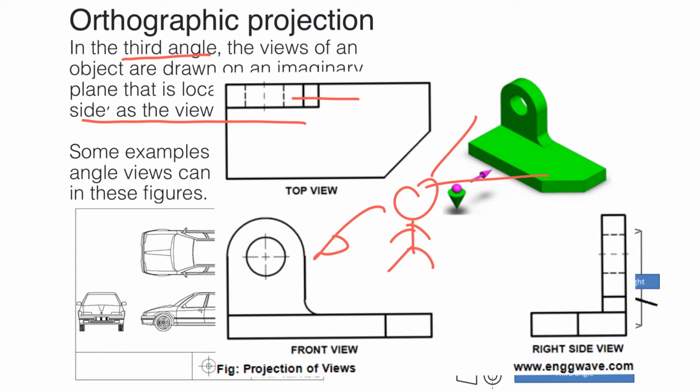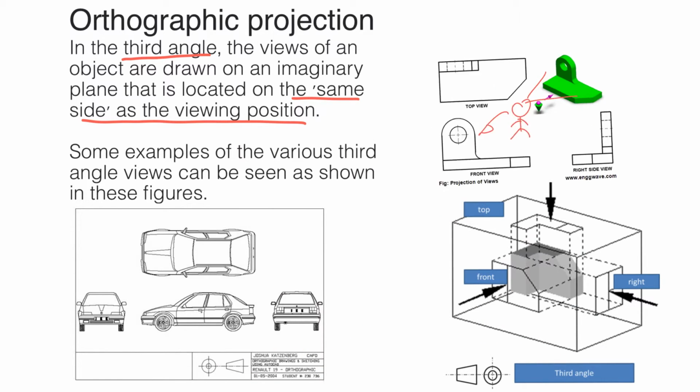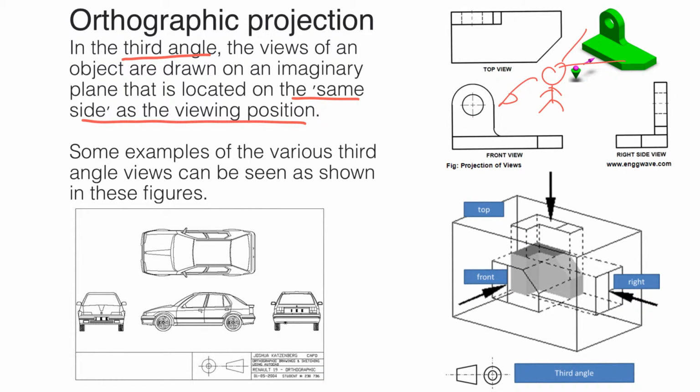Understanding the difference between the first angle and the third angle will enable you to differentiate between both projection types. It is good to know that the first angle projection is usually used in Singapore, for example, as well as in some European countries that adopt the Commonwealth system of design or angular projection.